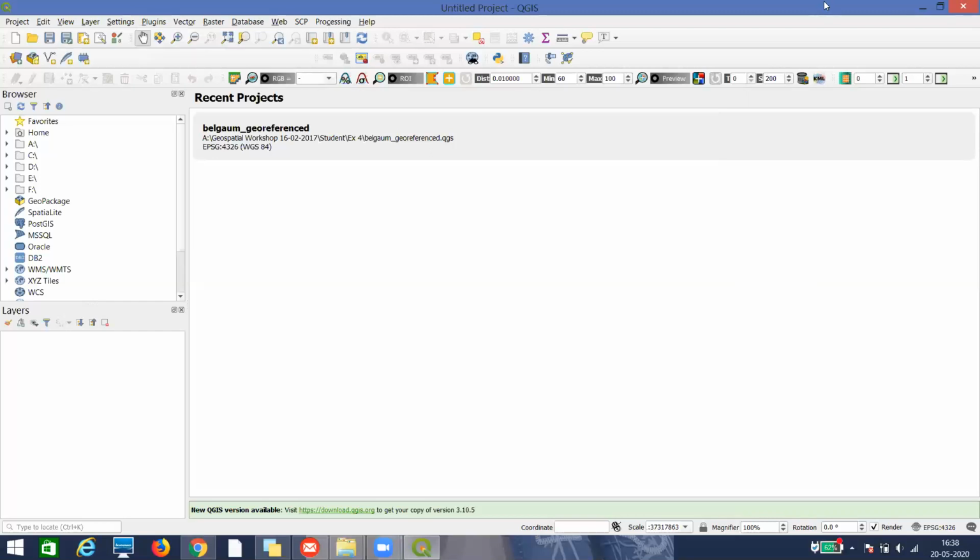Now in my class, what I'm interested in is the coordinate system. In QGIS, you have two coordinate systems, or any GIS software. I won't say QGIS alone. Any GIS software has two coordinate systems. One is your geographic, which shows your latitude and longitude, and the other is your projected. So any image needs to have the geographic coordinate first, and then I have to project it. The process of converting a normal image to an image with geographic coordinates is called georeferencing. So once an image is given geographic coordinates, you call it a georeferenced image.